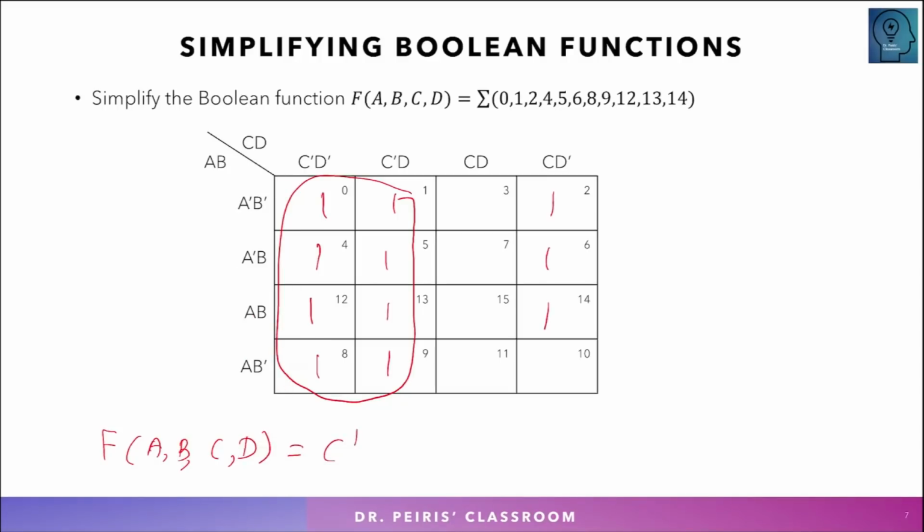C prime. Now how do we group this? This is only 3, so you cannot combine these 3. You can do these 2 and these 2, but that is not the best way to do it, because we said that the first and the fourth columns are adjacent, which means whatever the ones on this side, I can combine them with this side also.